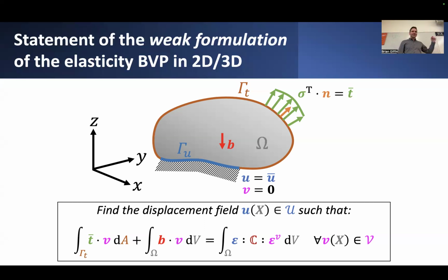So in other words, we have to pose some kind of Galerkin method or Galerkin approximation to this problem by choosing to represent the displacement field, and in fact the virtual displacement field as well, not as these potentially infinite number of material points that can deform independent of one another, but rather we can choose to represent the solution as being just the values of displacements at some discrete number of points.